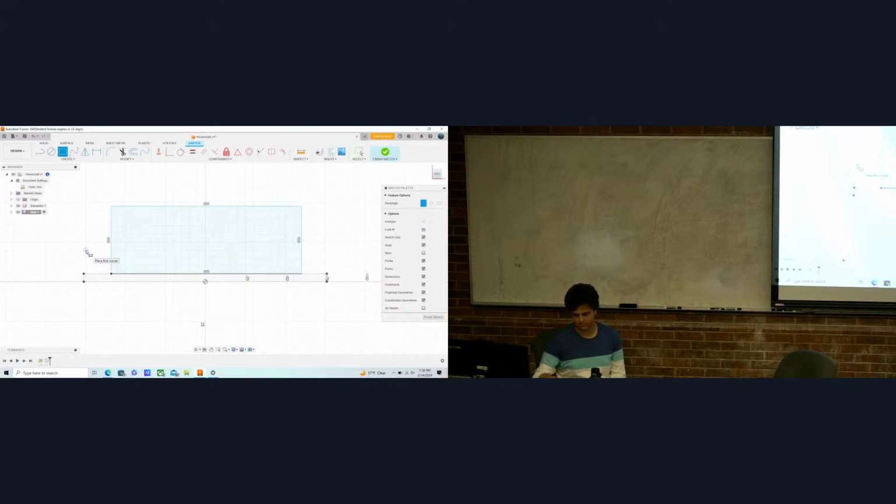Upside down. If you go up here to the cube and hover, you'll see those two curved arrow keys on the top right corner. And then you just rotate them like that. Yep. And then you'll project that base right there.